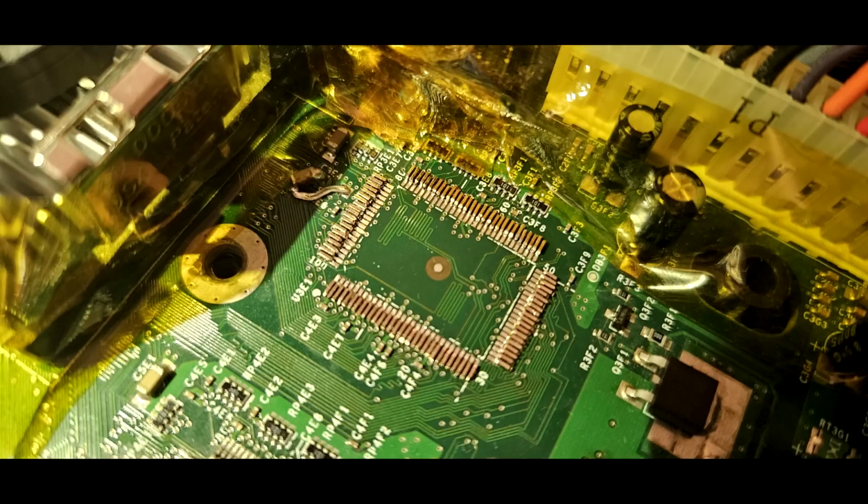And so I realized that there is a kind of redundancy here. The flex part is flexible, and the amount that it's flexible is not so much, just a bit. So I really don't need these pins that have a displacement of something like 7 millimeters. I don't have anywhere near that much displacement on the flex. So what I actually need is a rigid side on the Xbox, on the tester, and then I need some force from above that will press that flex onto the tester.